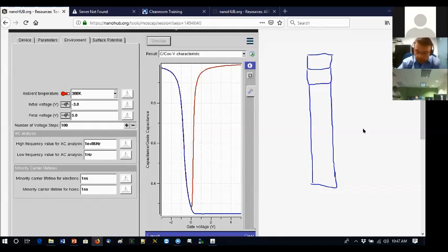What happened was we were applying negative voltages to the gate side first, and this was our oxide. That's our semiconductor. It's p-type, so it's rich with holes. Once we apply the negative voltage, all of the holes would try to go there, attracted under the force. And it's already a p site, and this portion would be even richer. So we would have a p plus kind of region here.